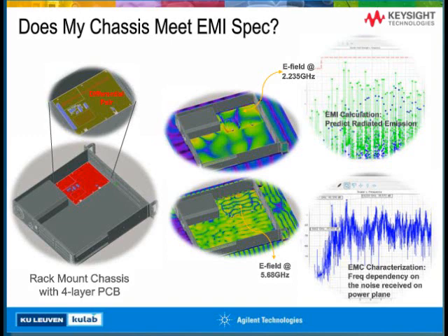Product may be failing to meet the requirements. And then from the EMI EMC behavior, what we could do is putting the plane wave excitation to the design and analyze how much noise is coupled to a certain part of the design. Here in this example, we put the power plane on the PCB, the board, and the blue trace on this slide is showing how much energy noise is coupled to the power plane on the PCB.